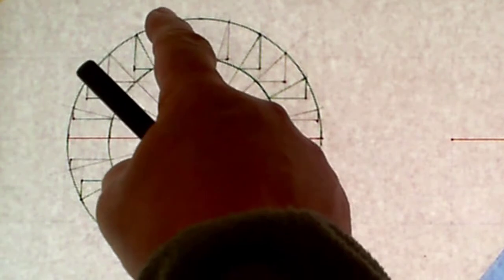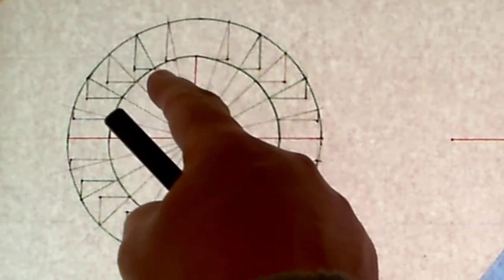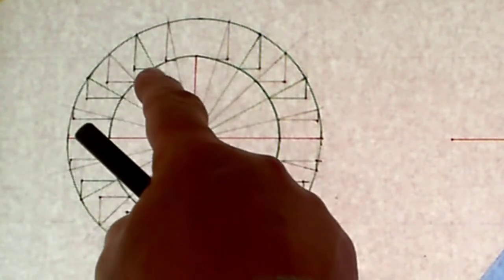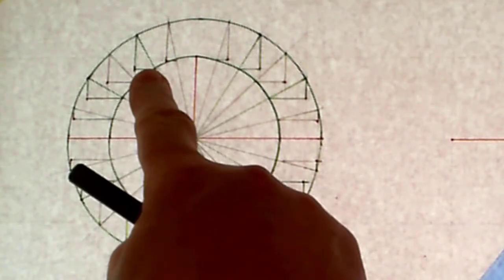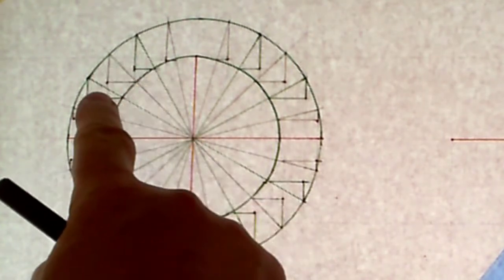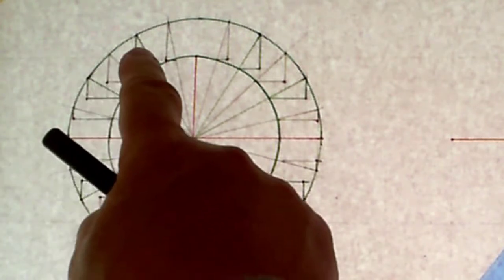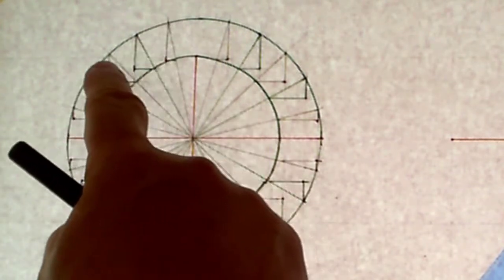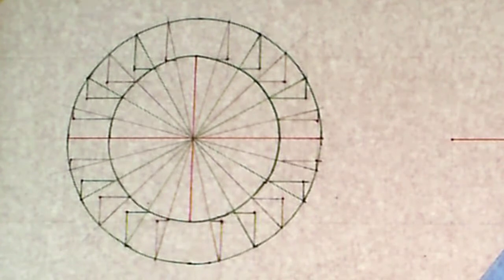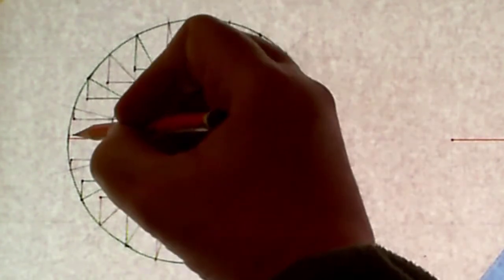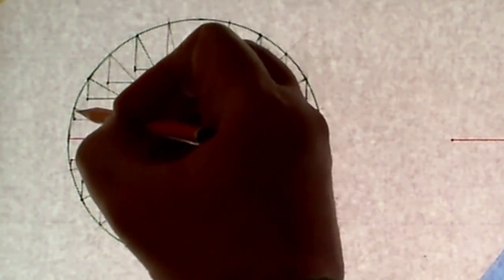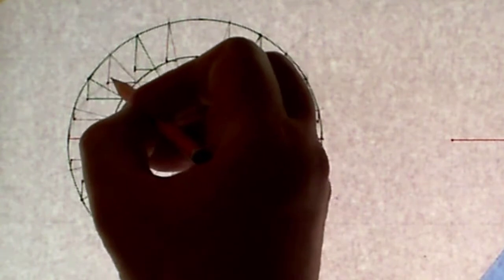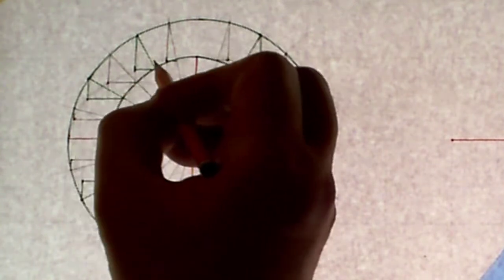So I'm dropping down from the outer circle, dropping all those points down and bringing where the same angle hits it on the minor axis. I bring them out to meet those points, those drops. So I established the different points on the circumference. Now what I'm going to do is I'm just going to draw that in, lightly connecting the points, and then I'll again use ink and a French curve just to establish that as a hard line.